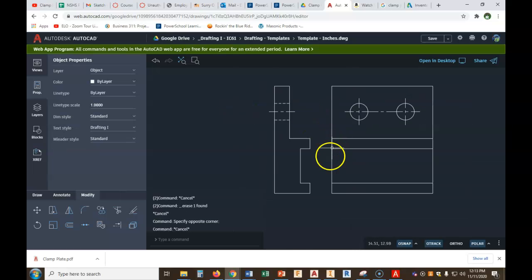So there we go. So this piece of information is telling somebody, hey, you need to look somewhere else. Something's happening. What's happening? Not just one, but two holes the exact same size are drilled in this piece. See the cutouts? Remember, rectangular, rectangular, rectangular, rectangular. There they are. Rectangle, rectangle, rectangle, rectangle. So that's all the views we need to draw to fully describe this object. We don't need the top, bottom, left, or rear. Those two do it. Okay?